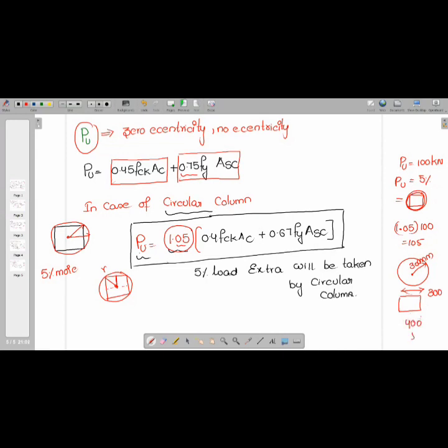Similarly, they do with 400 mm, 500 mm. With this, they interpolate and have observed that the load in case of a circular column is 5% more. Whatever results are in IS 456 are yielded by taking a number of samples. After collecting the samples, the Bureau of Indian Standards performs all the experiments and concludes the same for the circular column.